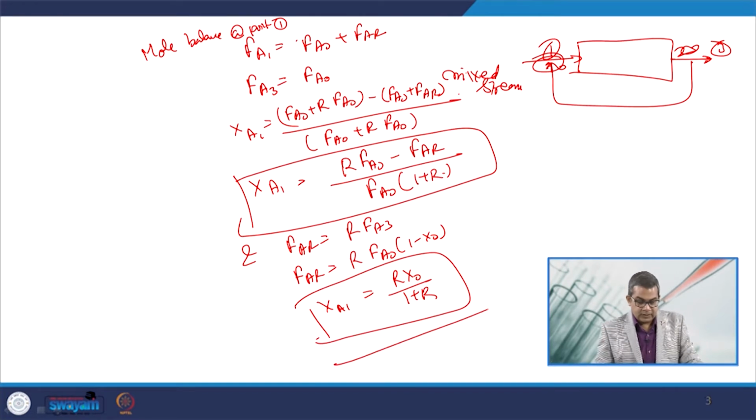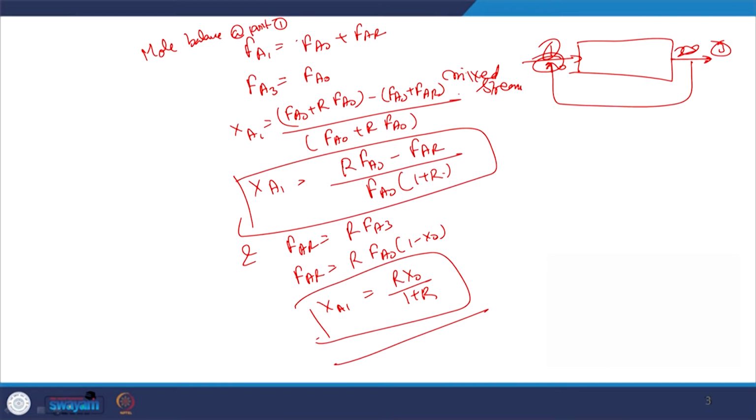So, this is the required equation, which is sometimes very useful for assessing things. Now, we can use the recycling in the plug flow reactor, because sometimes it is quite useful in the industrial approach. Therefore, to write the differential form of the performance equation for a plug flow reactor, putting the initial value of molar flow rate at the entrance of the reactor, (R plus 1) FA naught, with the conversion XA1, it can be given as such.